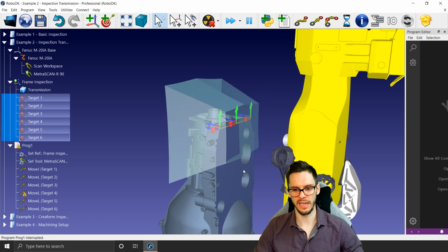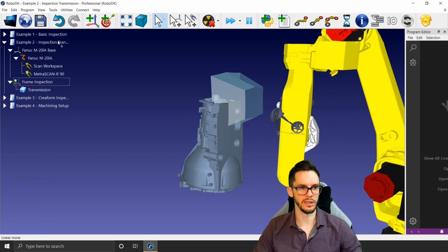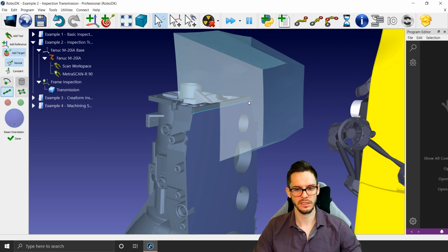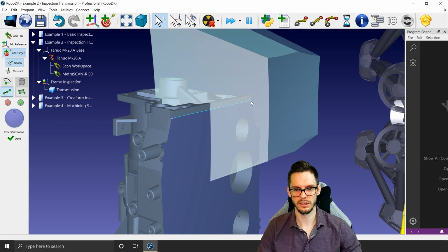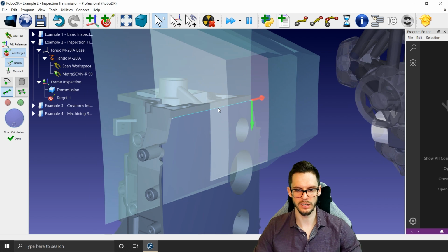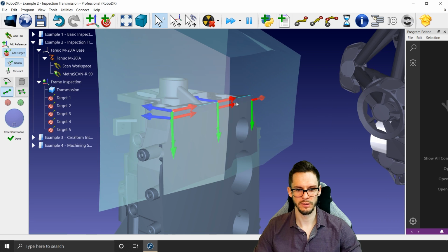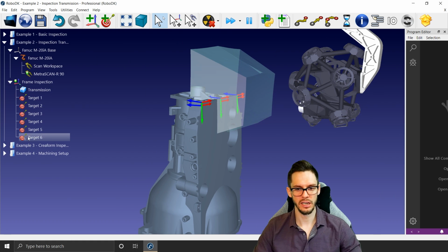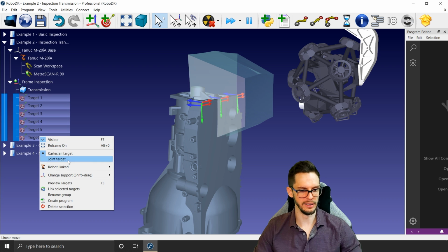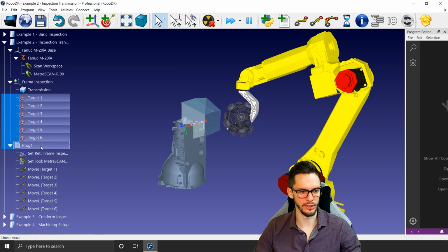And now, I forgot to rotate my tool before creating the target. So right now I'm not able to go upward as I'm hitting a singularity. So what I should have done is, again, teach target on surface, come here, and then rotate 180 degrees, just like that, create my first target, create my second one, my third one, fourth one, fifth one, and then the last one. As you see, I don't need to be super precise for it to snap on the end. So if I just create the robot program, now I have the robot program that I required. Okay.